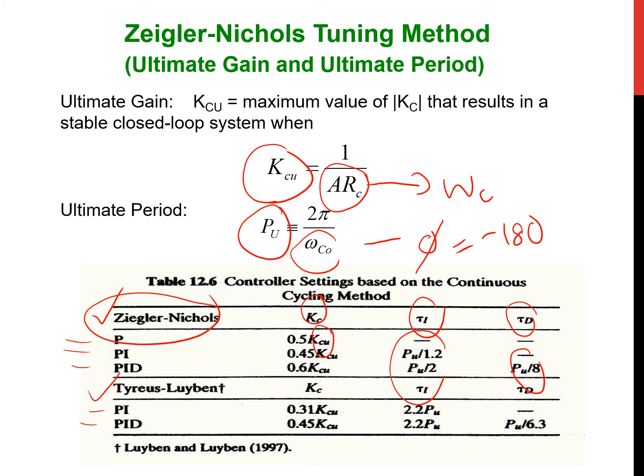And then we check whether it now falls inside the region of well-designed phase margin and gain margin: 1.7 to 4.0 for gain margin and 30 to 45 for phase margin. If not satisfied again, then you need to find another method. Maybe try Tyreus-Luyben, for example. You need to try until you get the range. Although if you keep trying and it's still not working, then both methods cannot be used, since they will contribute to an out-of-design control system.